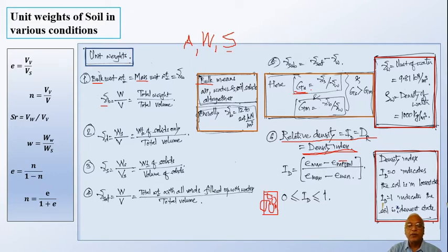Okay, now you loosen the soil completely, refill it without much of the effort being put onto the soil particles, then it will be quite loosely filled in a container. Then you try to calculate what is the voids ratio. So voids will be maximum, because of that what you get is E maximum.